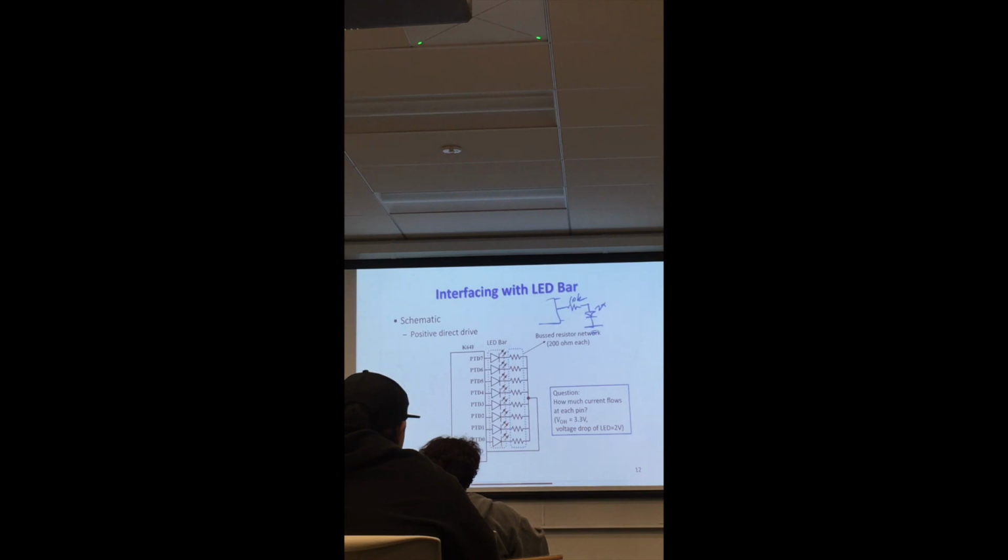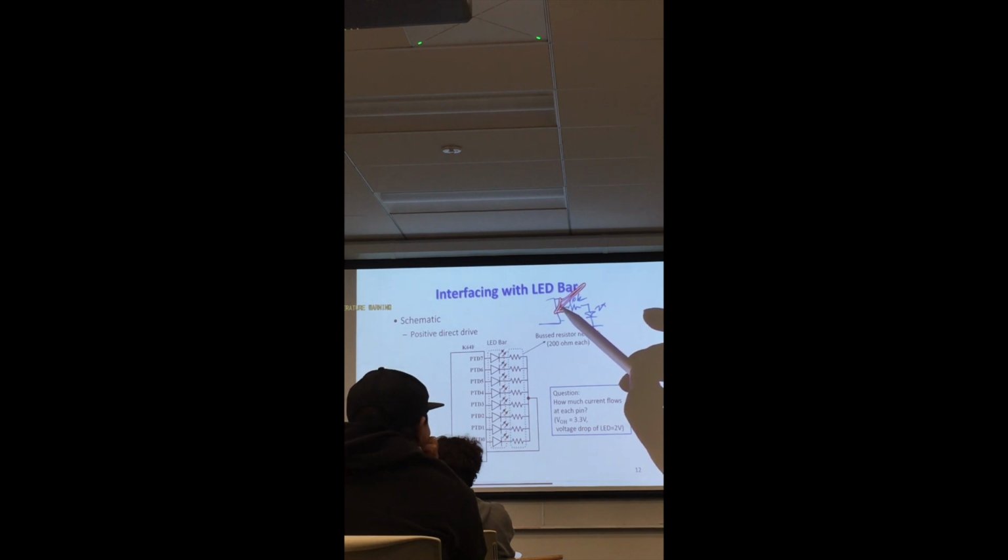You understand the question, right? So the internal pull-up resistor, if you enable it, will be 10K. Now you connect it like so on this pin, you enable the pull-up resistor, and you have such a connection. My question is, what would be the voltage in here? The pin will produce, which you will measure with the multimeter. So what would be the voltage?